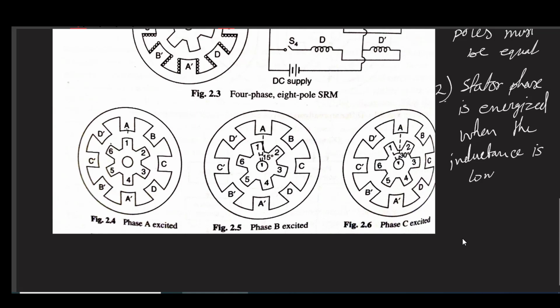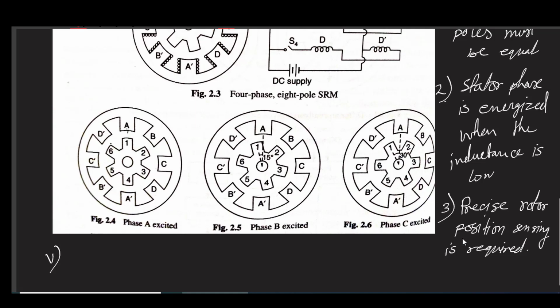Third one is in line with that. Fourth one is that the flux density is changing in magnitude and direction in the magnetic circuit when the rotor moves. So there is a chance of core loss. To reduce this core loss, we must laminate the rotor and stator structure.